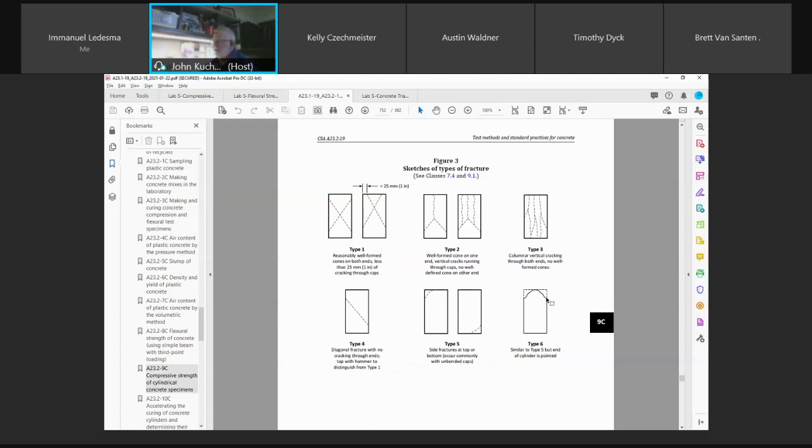When you have something like this, where the tops just break but the rest of the cylinder is intact, there is definitely something wrong with the cylinder. These are common, and these tell you that it's consistent, that the concrete's okay. So conical bond and long plane shear. For you guys, just call them all conical bond.